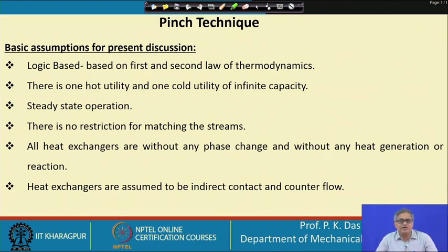We are considering steady state operation and there is no restriction for matching two streams. In practice, sometimes two streams, though they can give very good energy exchange, cannot be matched because they are at two extreme ends of the plant, and bringing them close is difficult. Or one stream may be very hazardous, so it is better not to put it in a heat exchanger with another stream. These kinds of matching restrictions are not there.